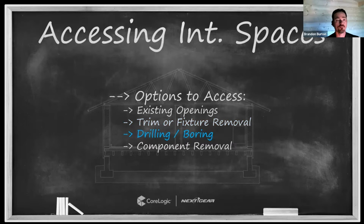Drilling and boring and creating openings. Hopefully this is in combination with the trim removal that we talked about just above, but that would be the next layer of invasive access into an interstitial cavity or void. And part of what will mitigate how severe this is going to be is your equipment selection. Because if we have the right specialty drying equipment, we can really minimize the openings that we create. If we don't have necessarily the best equipment for the job, we may have to make much larger openings. So there'll be a kind of a relationship between these two that we'll touch on.